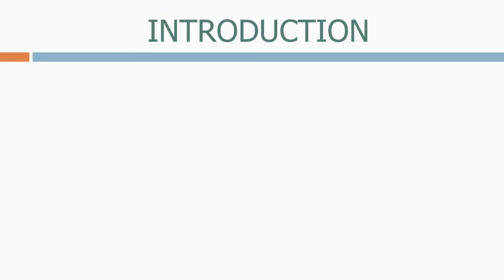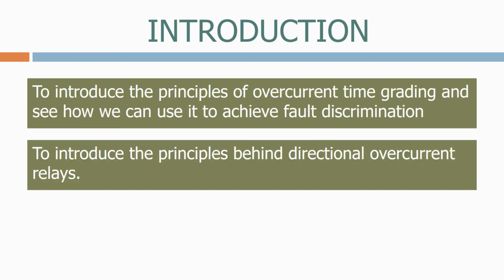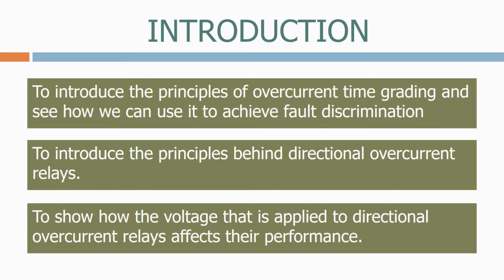The aims of the course today are to introduce the principles of overcurrent time grading and see how we can use it to achieve fault discrimination, to introduce the principles behind directional overcurrent relays, to show how the voltage that is applied to directional overcurrent relays affects their performance,